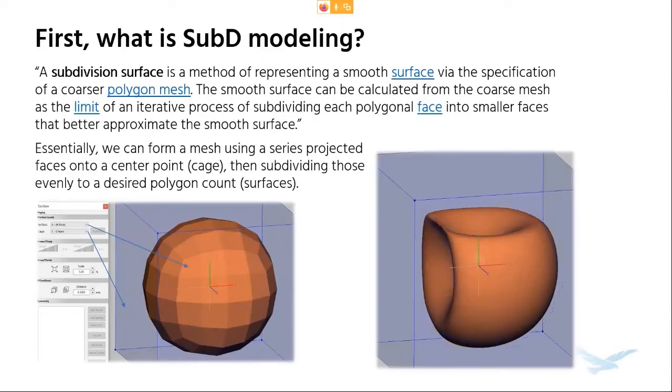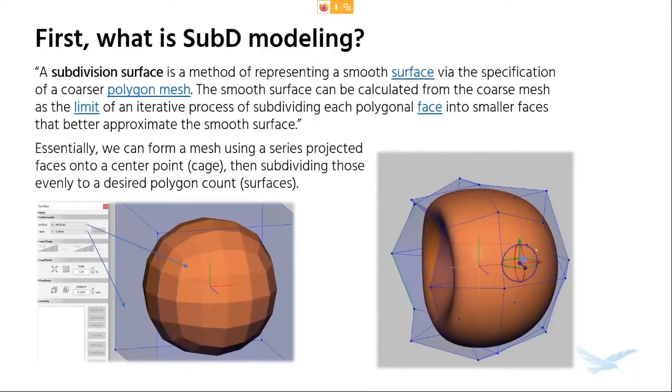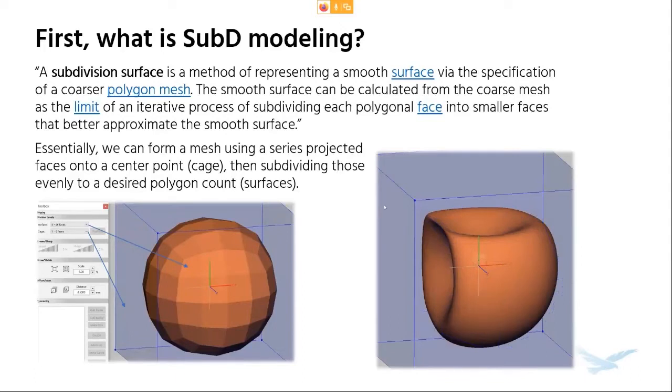And it's this projection method that allows us to create extremely smooth transitions between different parts of the faces without needing to worry too much about tangential splines or anything like that. So in this GIF on the right, you can see that I'm able to just push and pull two points around, and we create a really smooth transition between them, and it's automatically adjusting as I'm pushing and pulling. In the traditional sense of CAD modeling, we'd have to have a series of different splines, all stitched together in a tangential way. And then if we adjust one thing, how is it going to affect things down the line?